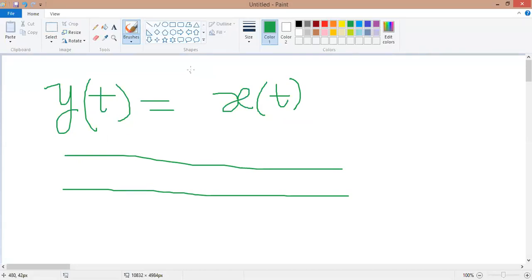So when the amplitude is transmitted as A, it may be found as A prime, where A prime is less than the transmitted signal A. So what do I need? I need to amplify it. That's why we need to amplify at the receiving end first. We have used an RF amplifier for the superheterodyne receiver. We want to amplify it first. Okay, nice.